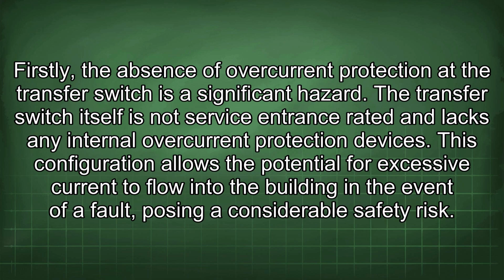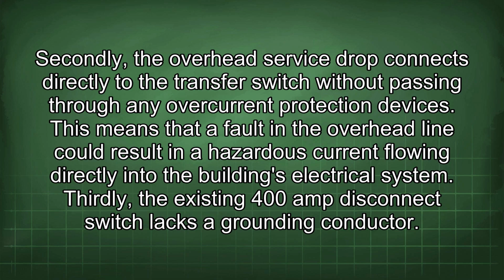The transfer switch itself is not service entrance rated and lacks any internal overcurrent protection devices. This configuration allows the potential for excessive current to flow into the building in the event of a fault, posing a considerable safety risk. Secondly, the overhead service drop connects directly to the transfer switch without passing through any overcurrent protection devices. This means that a fault in the overhead line could result in a hazardous current flowing directly into